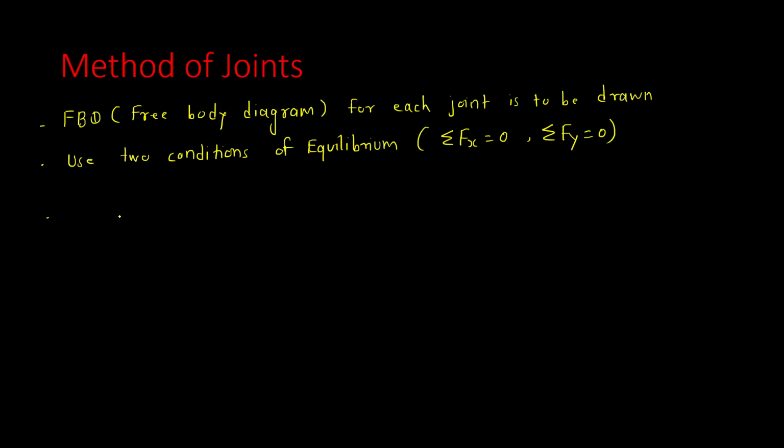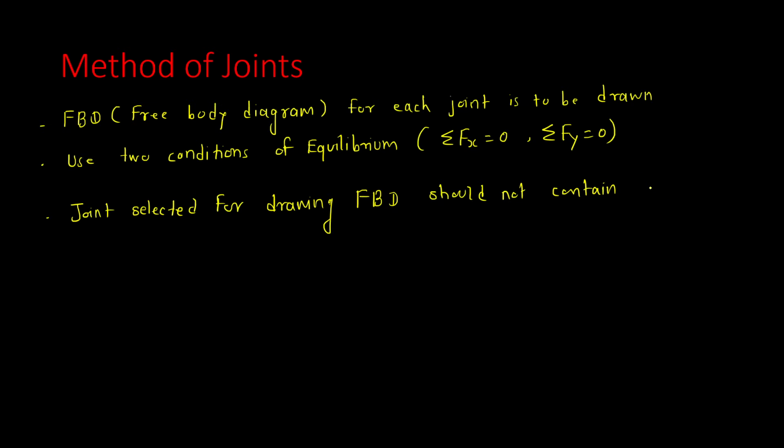Now whatever joint you are selecting, that joint selected for drawing the FBD should not contain more than two unknown forces.